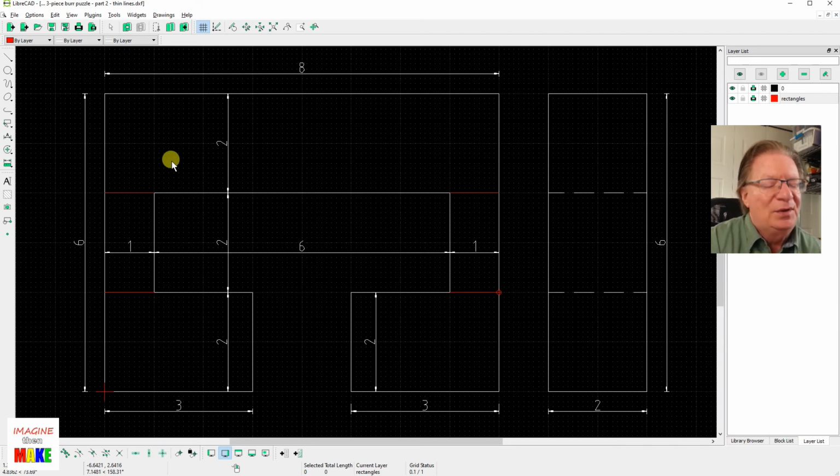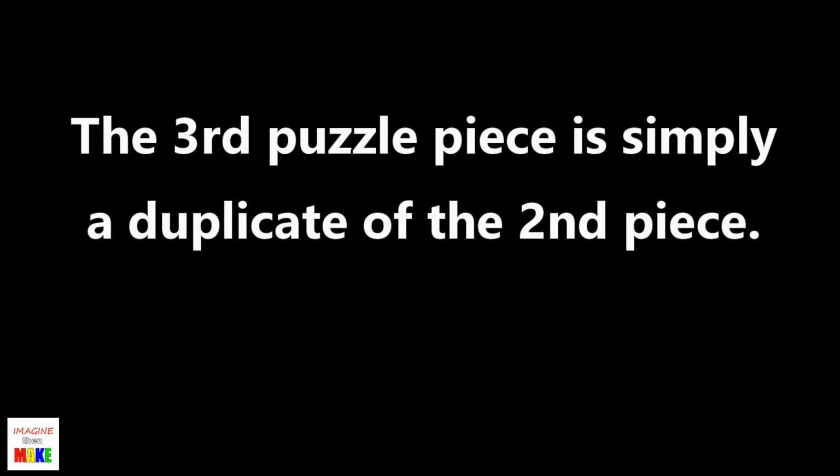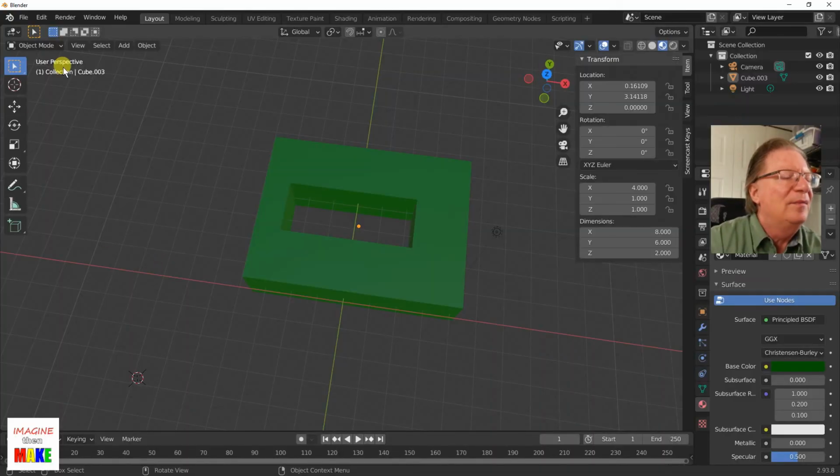So all I did was do the same thing in Blender and create the five boxes and join them corner to corner. And then once all that was done, select all five boxes and use the join command to set one origin for the whole piece. And then for convenience, I move the origin to the middle of the geometry. Okay, so that describes how I modeled the three pieces.